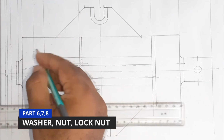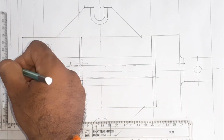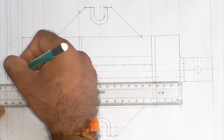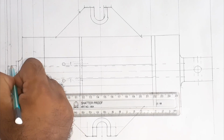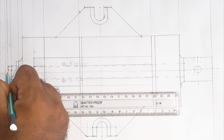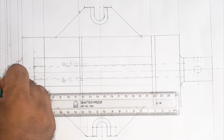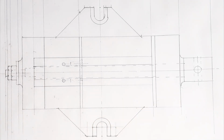Okay. So like this. So next is part number 8. So this is the part number 8. So we have to join this one. So next we have to draw this arc. So we will draw this in the free hand arc like this, or we can use the circle to draw the arcs. Okay. So then darken this line. Now this completes the part number 6, 7 and 8. So this overall completes the machine vice in the top view.